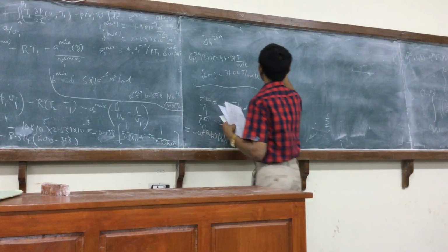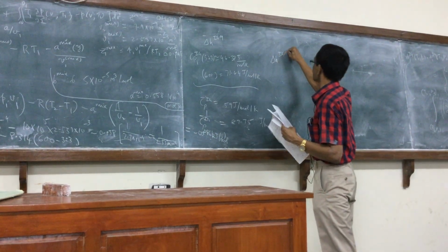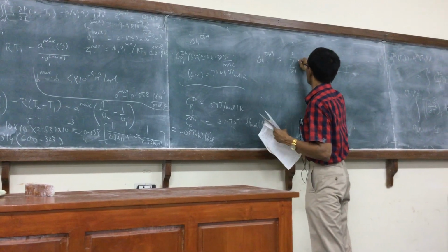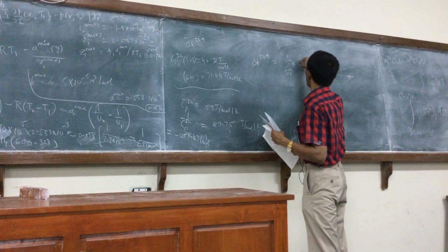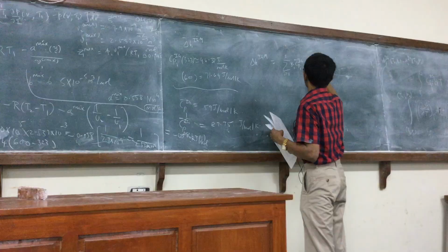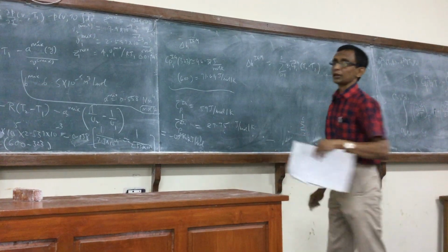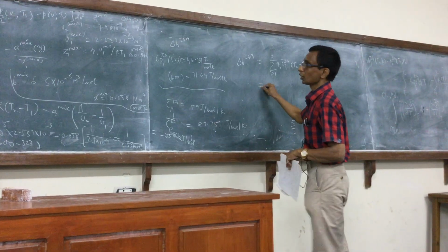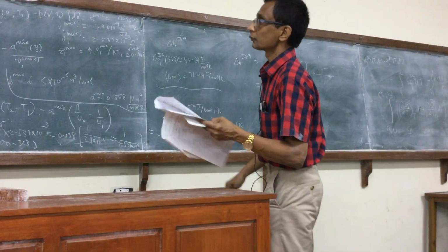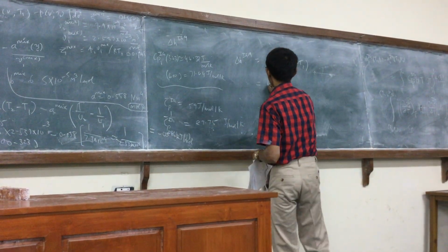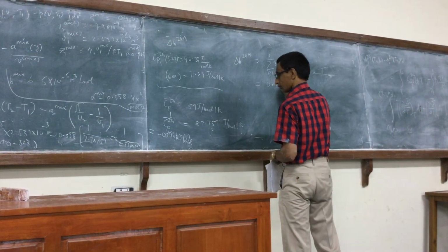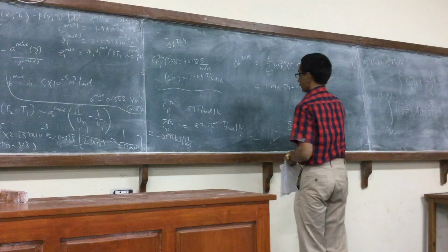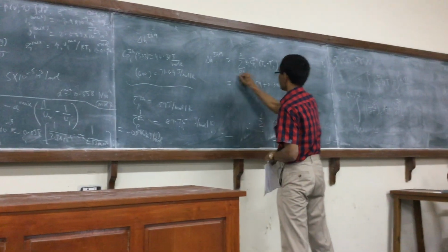So now the delta H IGM, as we have seen for constant specific heat, is the sum over i equal to 1 to 2 of yi Cp,i IG times (T2 minus T1). So this would now be 0.7 times 59 plus 0.3 times 87.75.